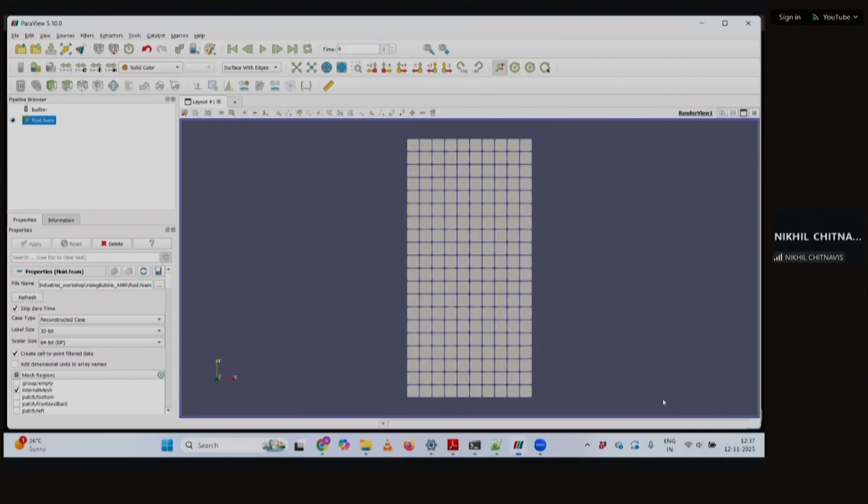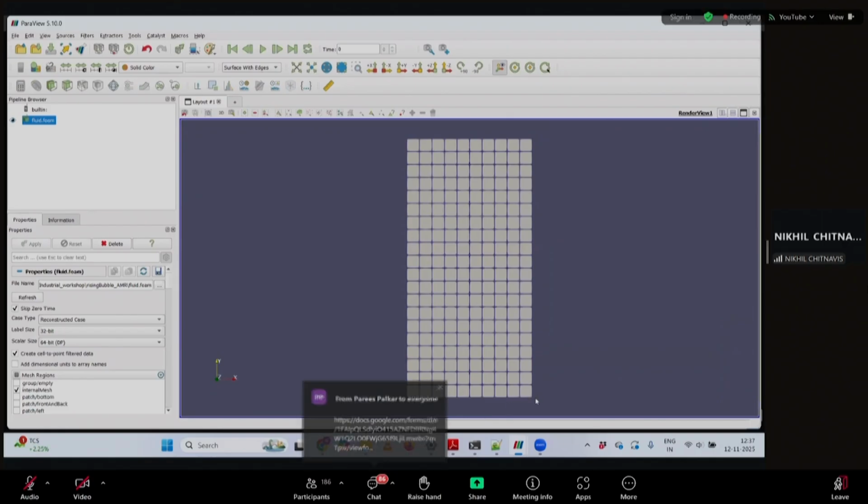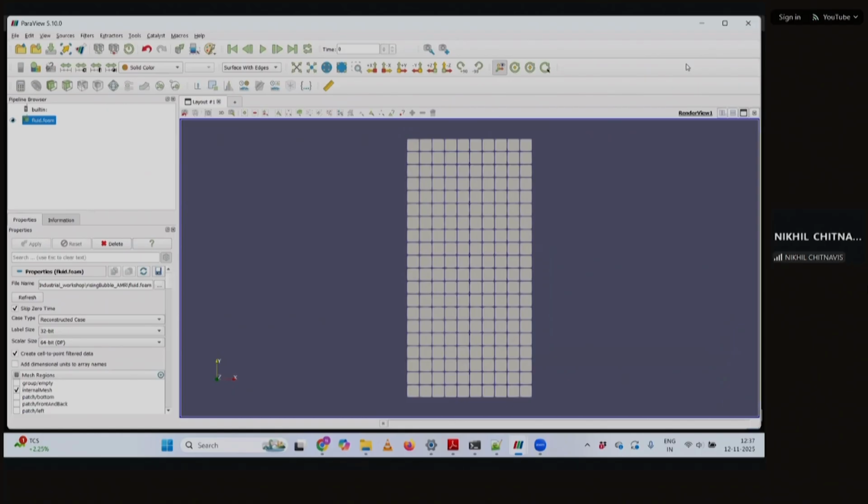But for the adaptive mesh refinement, this much coarse mesh we are giving. So the idea is we're not going to refine the whole domain. We're only going to refine the interface, which will help in speeding up the simulation also. And the maximum refinement near the interface we are giving as 40,000 total mesh.